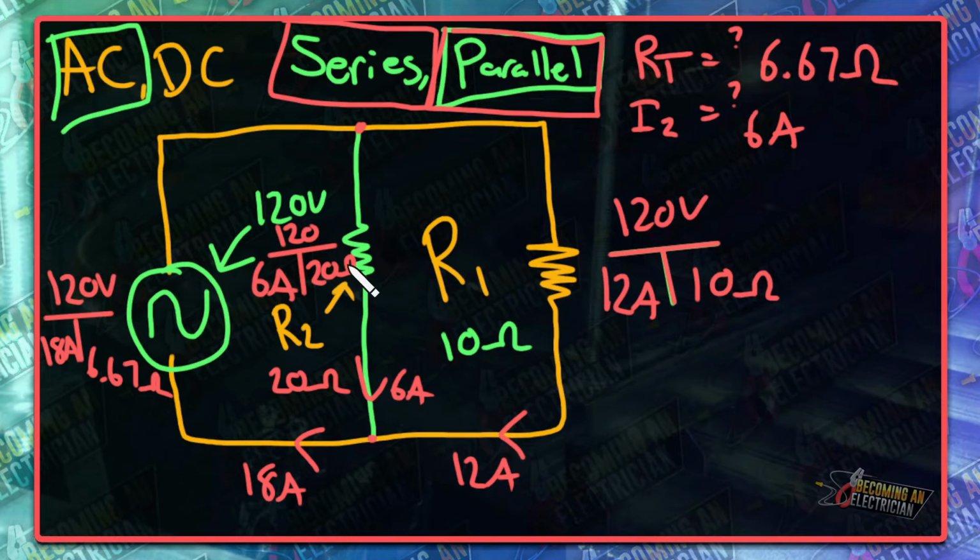So in a series circuit, we would actually have 30 ohms. But in a parallel circuit, I just showed you in the calculator, you had to do that kind of funky inverse stuff, right? And then the rule is that the actual total resistance has to be less than any single resistor. So if you had another one right here, and if it was 8 ohms, you knew that this still satisfies that kind of test. Okay, so once you understand these basics, that's what's happening.